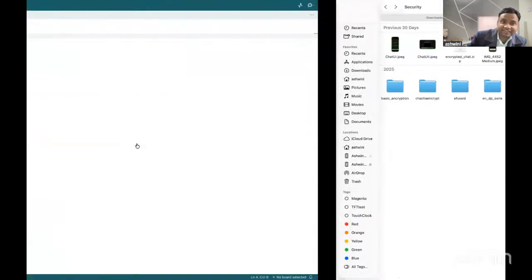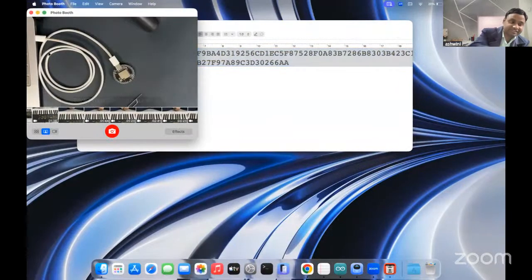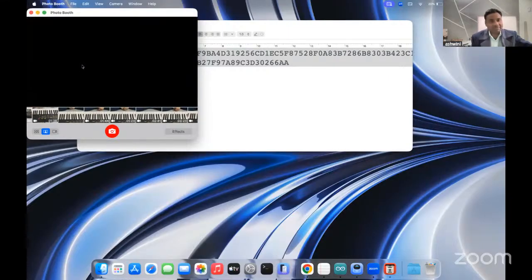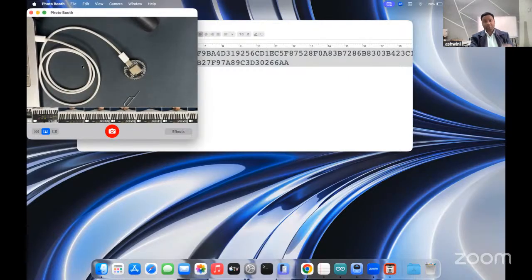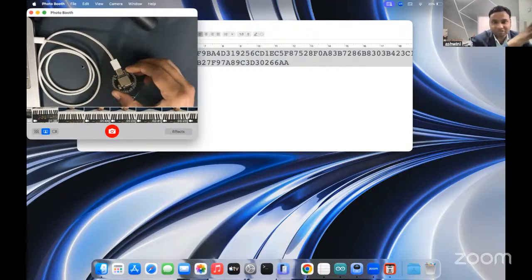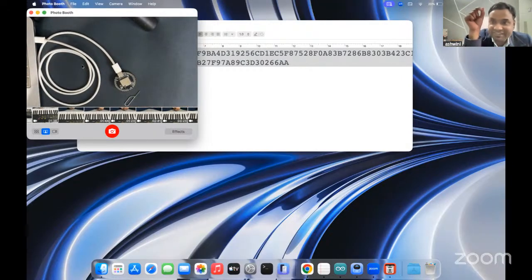But here in the Indus board, there is already a true random number generator present in this board. You do not need to buy one. For other IoT devices, if that is not present, you need to buy those chips and add them to create the random number. Then, based on that random number, you can use it as an OTP or a password generator, or for creating the encryption keys that we used earlier in the past code. But here you do not need to do all those things, because the random number generator chip is already there in the board.